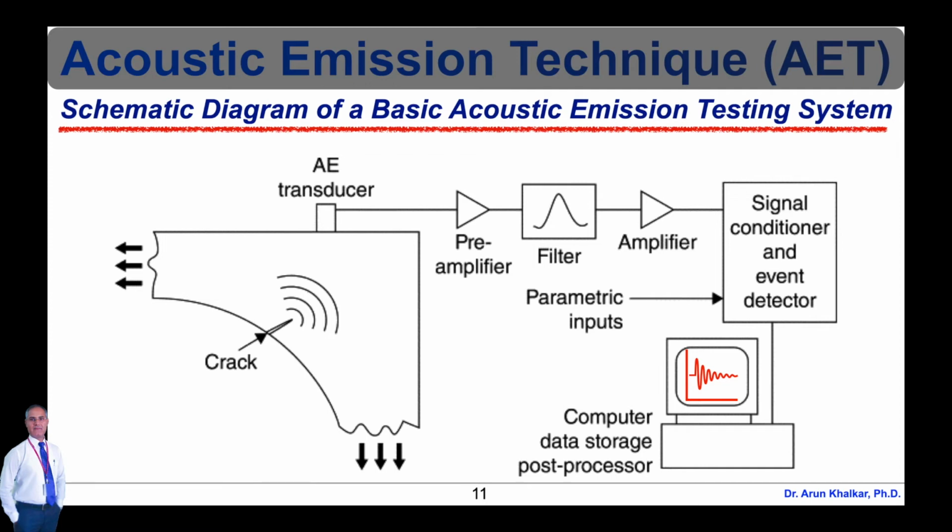Each time the threshold voltage is exceeded, the measurement circuit releases a digital pulse. The first pulse is used to signify the beginning of a hit. A hit is used to describe the AE event that is detected by a particular sensor. One AE event can cause a system with numerous channels to record multiple hits.